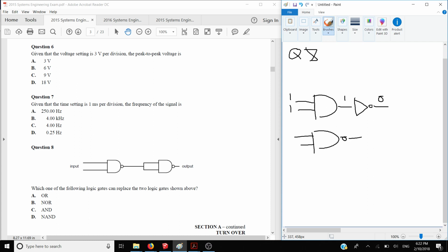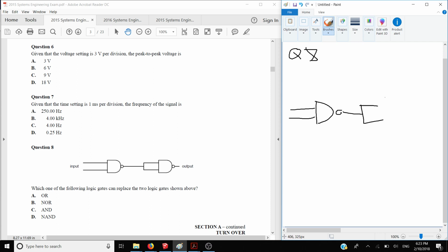Okay, so what does that mean for us? It means that any situation where one or both of your inputs are low, the output is going to be high. Okay, so I might just draw this out, because you could scribble all over this thing if you were actually working on the exam. So I might draw the whole thing out. So there's our first NAND gate, and that goes in, it just branches off, and that goes into our second NAND gate. Again, sorry for the terrible drawing.